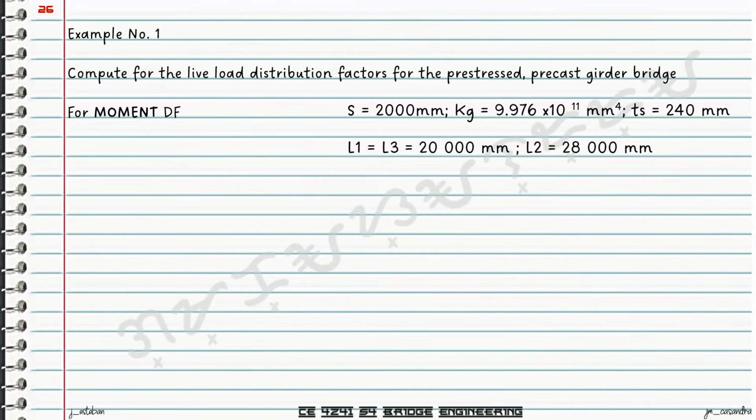So next, we solve for the moment distribution factor for the exterior beam for span 2. So again, from the table for one design lane load, we'll be solving this through the lever rule. Since we have the same cross-section, or same properties for our cross-section, basically we'll arrive at the same value of the distribution factor, which is 0.846.